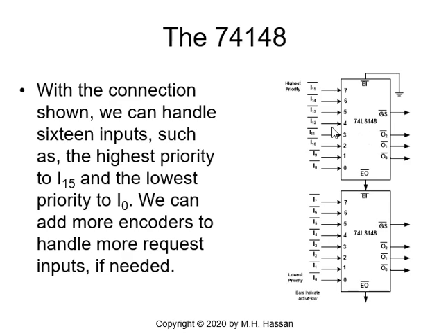But if any input from I8 to I15 is active, this enable output will be high, and this chip will be inactive. So this will give you a priority.